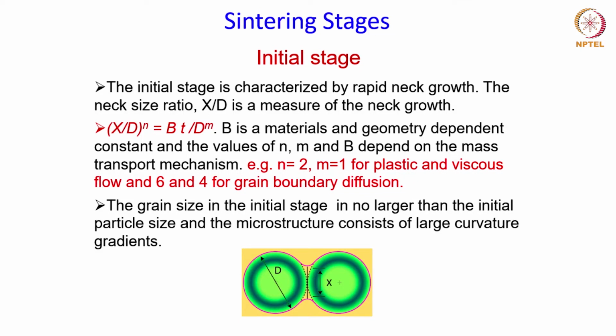Now, the sintering process occurs in stages. This densification that you have during the process of sintering does not really take place at once. There are stages at which different phenomena can take place, leading to growth of the neck and pore closure, and ultimately when all the stages are completed, you will get a fully dense product.